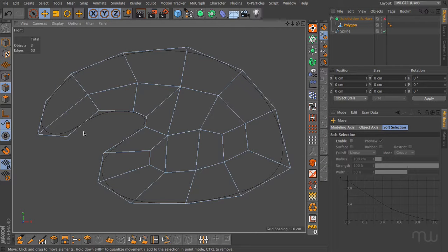Now, to get this to run in a continuous loop around my shape, I'm actually going to subdivide this surface, as currently I don't have enough geometry to accomplish this task, but it should be pretty easy once we've added another iteration of subdivision to this. And this is a fairly common technique when you're modelling: you build the shape in a very low poly way and then subdivide it by one iteration, which gives you more geometry to play with.